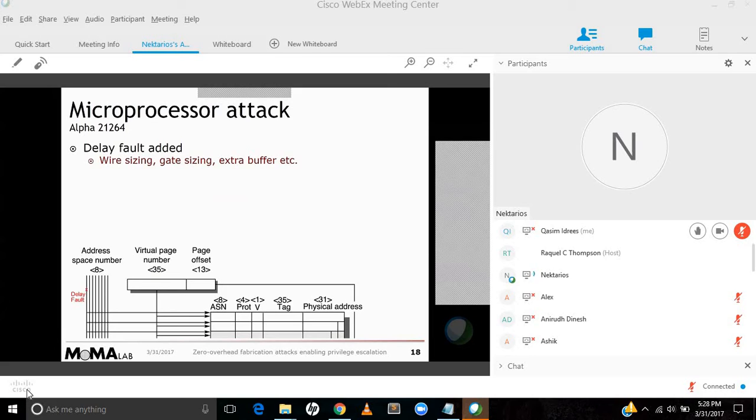As you can see on the left side of the image, this delay fault is on the most significant bit, and it will make the processor choose which row on the table we are interested in. And if the processor does not read the signal quickly enough and reads an incorrect value in the most significant bit, it will select a different row.